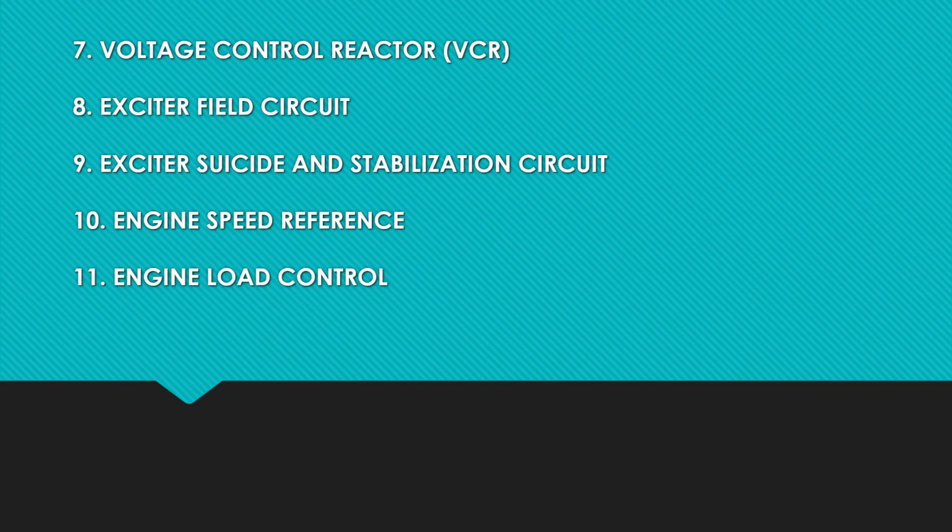The more the DC current in the DC winding, the more the AC output. The AC winding is connected to one of the secondaries of the oscillator transformer. One DC winding is connected to AR output through a series of resistors to control the output voltage. It provides isolation between the high voltage of the rectifier and the control circuit.